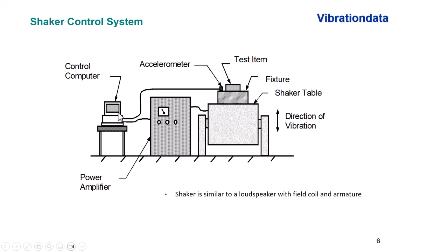It's a voltage time history, but the computer can apply the accelerometer scale factor to determine the G's per time, and then do whatever Fourier transforms or other calculations are needed to get a PSD in the case of random vibration. Now the control computer will then adjust the output signal in order to better meet what the specification is.